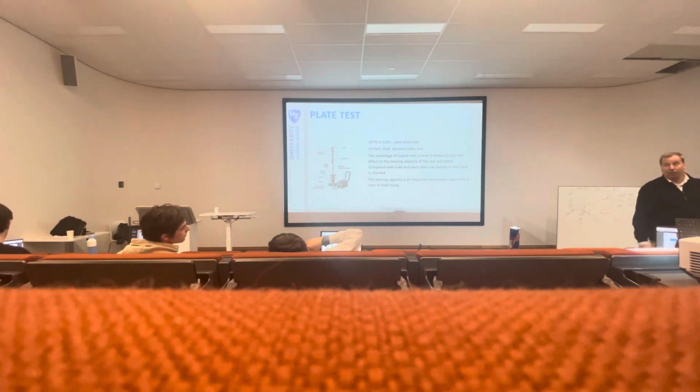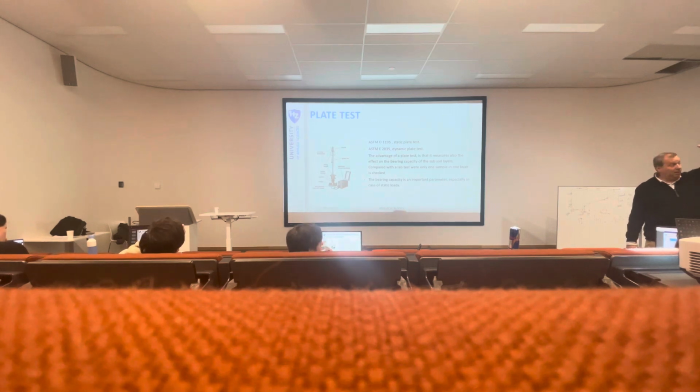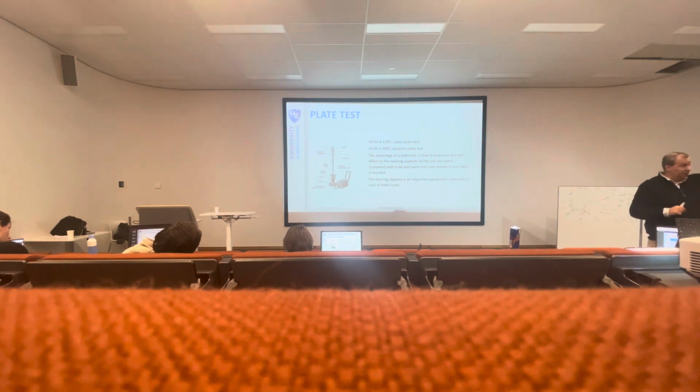EV1 means you push on that plate on the soil and you get a certain deformation with a certain force. Then that's EV1. Then you take off the load and then you push it back. And then the difference between the first deflection and the second one is EV2.